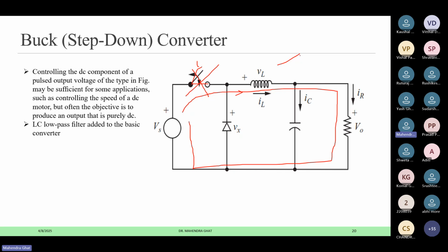But as the inductor current is there, it will not directly go to zero, even though you have isolated this source by turning off this switch. The current will not interruptly go to the zero value. But what it will do, it will either remain constant at that value, or if any loading is there, then it will try to reduce with a slope.